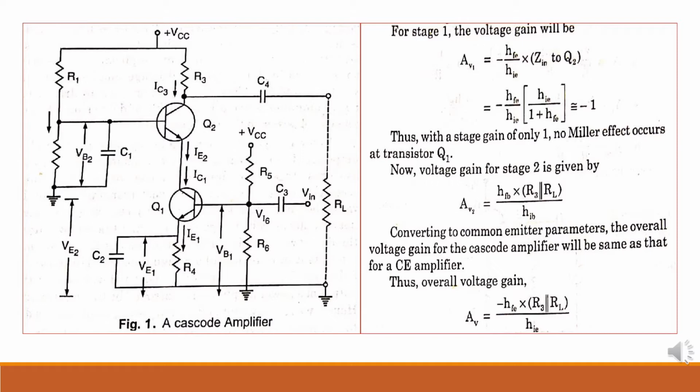Here we can see that the transistor Q1 and its associated components operate as a common emitter input stage, whereas the circuit of transistor Q2 operates as a common base output stage. This type of arrangement is designed to provide a high input impedance with low voltage gain. Why should we use it? Just to ensure that the input Miller capacitance is at its minimum value, with a common base stage providing good high frequency operation.